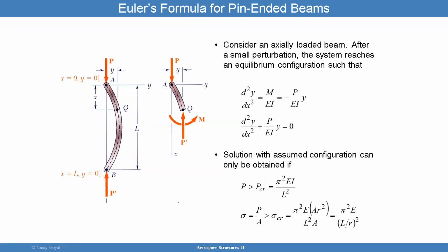In fact, if I give any of you a ruler and I ask you to apply loading to that ruler, without having to go to the labs to determine when buckling occurs, it is going to be quite interesting, because just by using this formula and knowing what pi is, which is 3.14, and the modulus is E, and I is the moment of inertia, and L is the length, with that information, I can calculate buckling analytically.